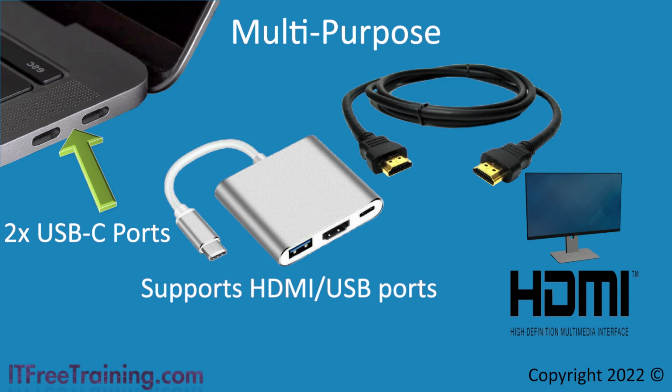are running higher resolutions, for example 2 4K displays, and then try to add USB functions, this means there is a lot of data running over the one cable. If you are doing this, consider breaking the data up. For example, running video off one USB cable and USB off a different one.